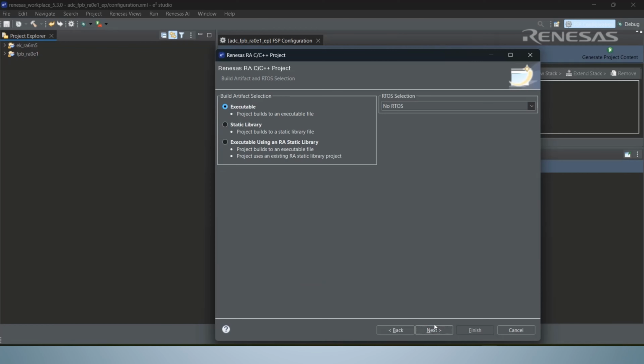Executable programs are directly compiled into .hex, .bin, or .elf files that can be directly run on hardware devices. On the other hand, static libraries are collections of pre-compiled code that can be linked into an application at compile time. They typically contain usable functions, classes, or code modules. When we compile a static library, the output is a .lib or .a file. We cannot run a static library on a hardware device. We need to link it with an executable at compile time.